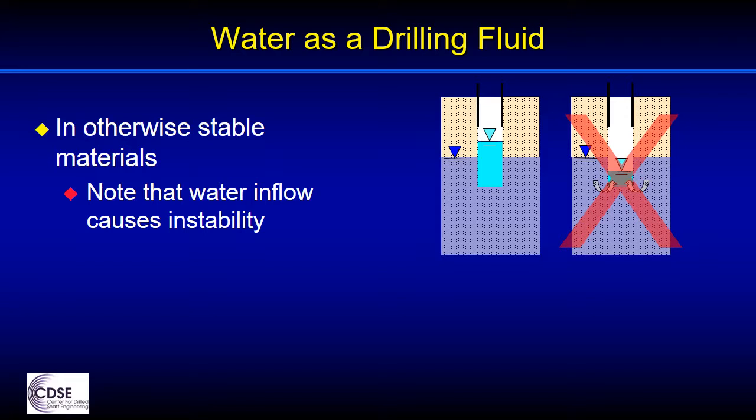If we see significant amounts of water flowing into the hole, the right thing to do is to flood the hole by adding water so that the inflow is reversed. If we just wait until the hole fills up, that's not going to work, because every time we remove some material, there will again be a situation of inflow that can destabilize or bring in materials from the surrounding soils.